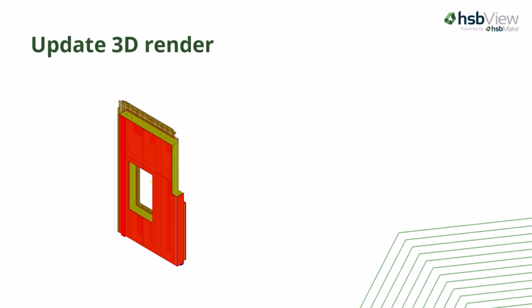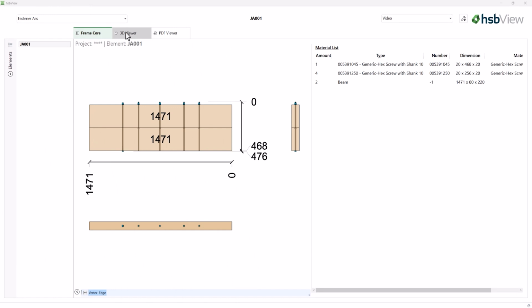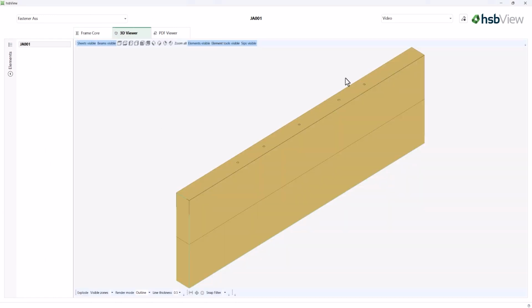As a final thing, I'd like to have a quick run through some of the changes we've done to the 3D rendering inside hsbView. As you can see, the 3D viewer now opens automatically in an isometric view, and we have a parallel viewpoint rather than the perspective. This makes it easy when trying to use the features that you're used to with the dimensioning tools, etc.